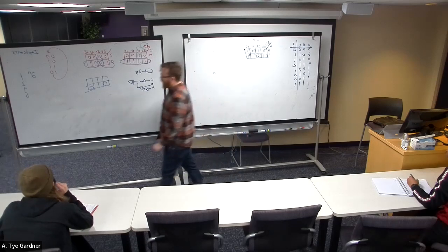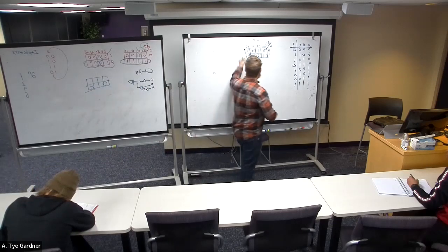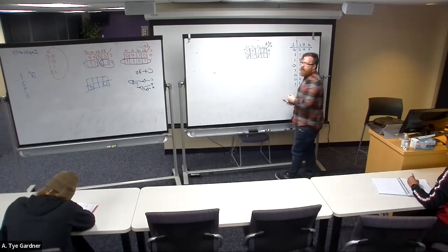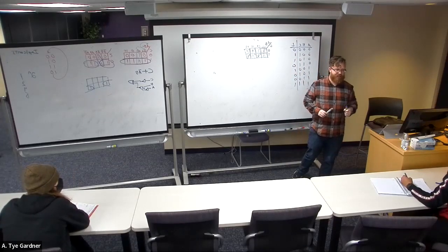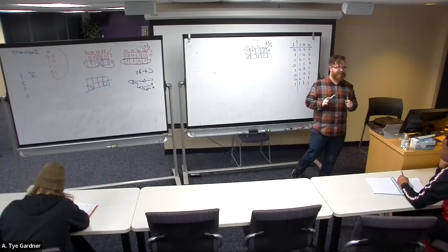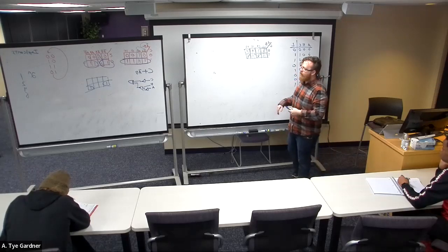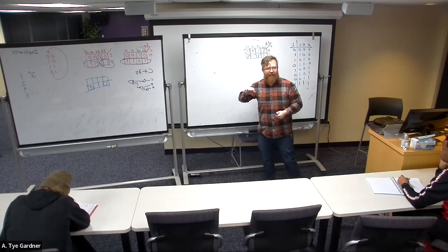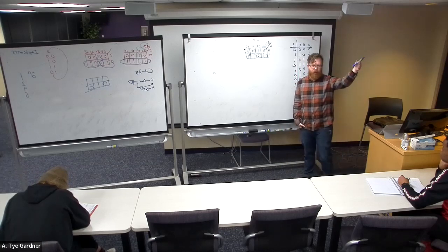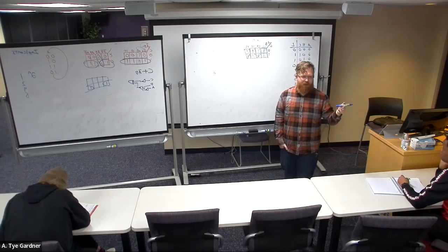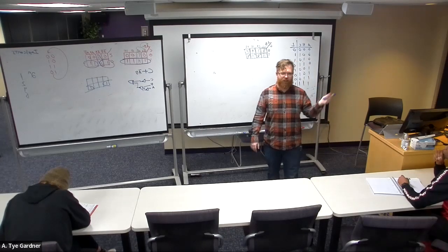So I am allowed to circle ones. I grab my pen, I circle each and every one because I need complete coverage. Okay, coverage, that's the term. I have circled all of my ones. In order to get a minimum expression, if I ask for minimum expressions, that means you need to start by drawing the biggest circles you can and fill in the rest. There's a whole design rule list that the book has that you can go read, but it boils down to circle the biggest things you can find first and don't be afraid to try again.